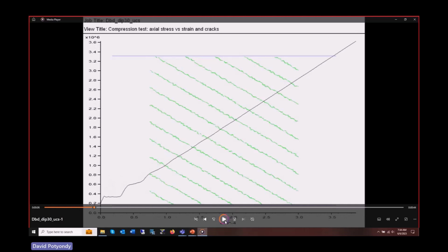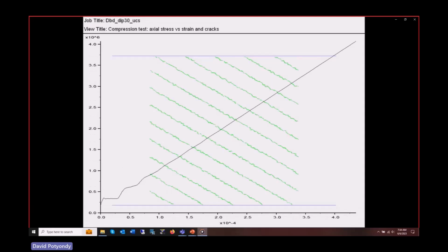So look at this. We just talked about that. We're starting the test. We instantly started loading it. So there's this wave going back and forth a little bit. This is stress and strain that we're measuring. But you can see how it damps out. And now we're just pretty much going straight up, loading this thing up. Notice there were no breakages at this point. All right. We continue to load.